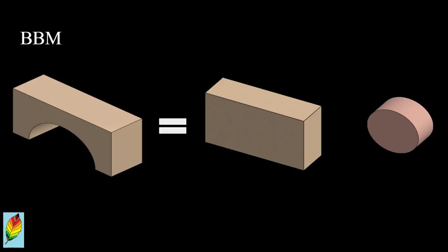Recalling the video on Boolean-based modeling, we know that we would need to subtract the elliptical cylinder from the rectangular prism. You can adjust the node and edge sets to center the elliptical cylinder in the horizontal direction, and place the horizontal elliptical cross-section diameter on the bottom edge of the rectangular prism. This process can be completed using a variety of CAD mating techniques, which will not be discussed further here.